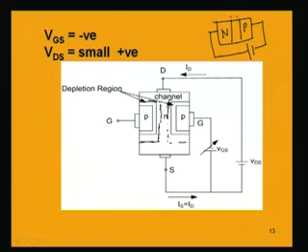Mind it, we are not changing the drain to source voltage, it is constant. So basically the gate to source voltage is having a control on the drain current. When we have this gate to source voltage negative, we are having a hold over the drain current, because the drain to source voltage is not changed, it is a constant voltage we are applying.